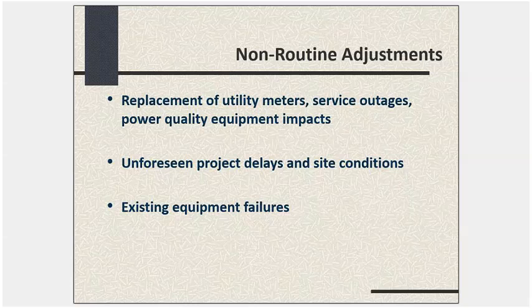Okay. So how important is calibration of these measuring equipment? Well, I'd say it's sort of a routine thing. Most ESCOs, anytime they're using field equipment, will show you a calibration certificate for it as part of their M&V plan to show that, this is what we used to measure power or runtime or whatever it was, and this is the instrument we used, and this is how we calibrated it before we took these measurements, or this is its most recent calibration time. I mean, you don't have to calibrate them every week, but they'll show you a current calibration certificate.